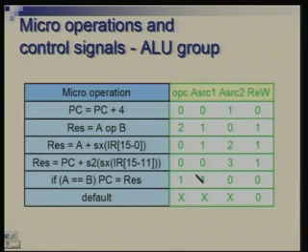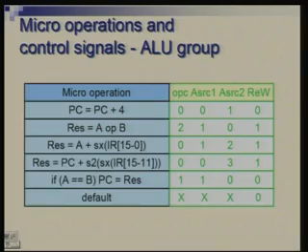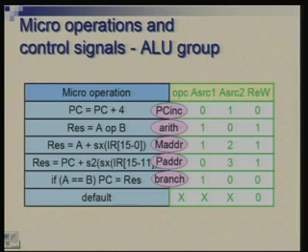Okay. So, now with this done, we have seen the relationship between micro operations which we picked out of that flow chart, and how they assert various control signals, what values they imply for various control signals. The names of these are PC increment, arithmetic, memory address, PC address, branch and no operation.